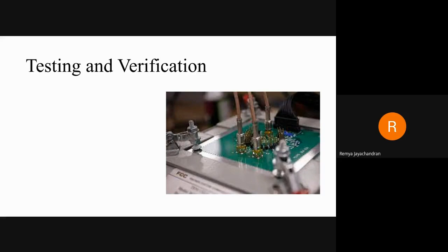So if you want to do your circuit design in a new device architecture, you can go for the first, you can model the device and extract the parameters from that and develop a compact model, a SPICE model for that, and then you can go for the circuit design and do all these steps, and finally, the final product you can test and verify whether you are getting the expected response.